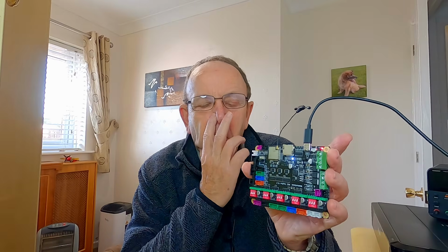And if you connect up to your power supply, nothing happens. There is a jumper on here that says to use USB power. It's got off USB power, but we're on USB power at the moment because we're not connected to any drivers or anything. So make sure you've got that right if you're having problems with it.